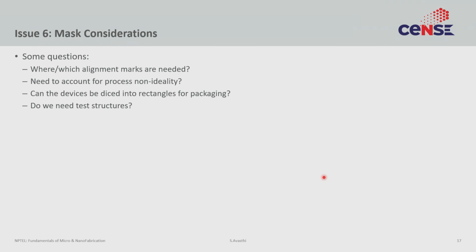Do you need test structures, right? A lot of people make a device. You want to make an FET, great, a transistor, you make a transistor. But if you just make a transistor, and if the device doesn't work, you have nowhere to start to find which process failed. Very important to have a whole bunch of test structures.